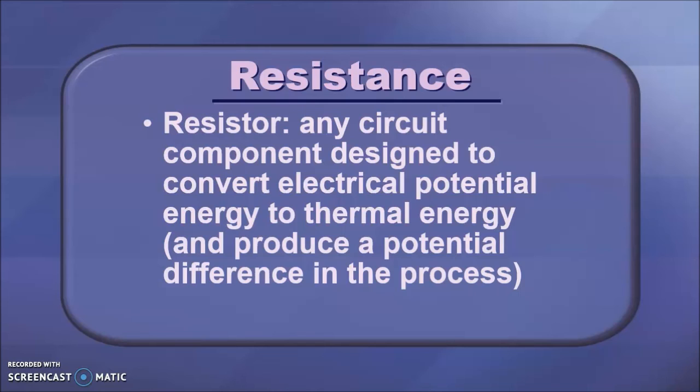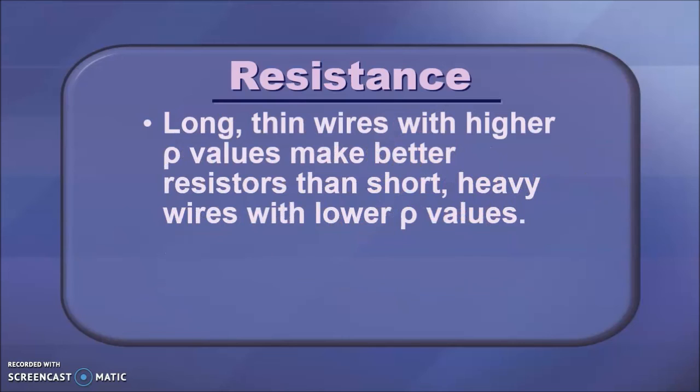And long, thin wires with higher resistivity values make better resistors than short, heavy wires with low rho values. So if you ever want a good resistor, you would typically want one that has long, thin wires.